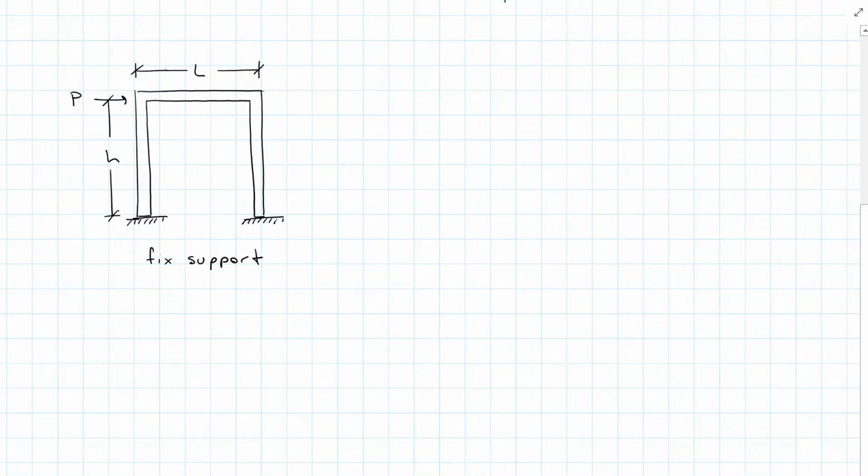Similarly, if I have a fixed support, it's going to deform something like this, where again I have this swirl at the top here where I have zero moment, but with the fixed end, the moment is now zero towards the middle of the columns instead of at the bottom like the pin, because the moments resist rotation. So it's going to come up and then rotate.